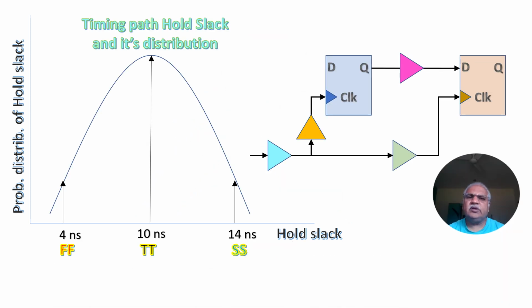So far we have understood how the MOS transistor, whether NMOS or PMOS or of a different VT, how their process distribution and different corners, like typical corner, slow and fast global corner, the different PVT corners and VT, will change, and the defects parts per million. However, if you apply the MOS transistors, because in a timing path there will be many transistors, cumulatively how will they play a role?